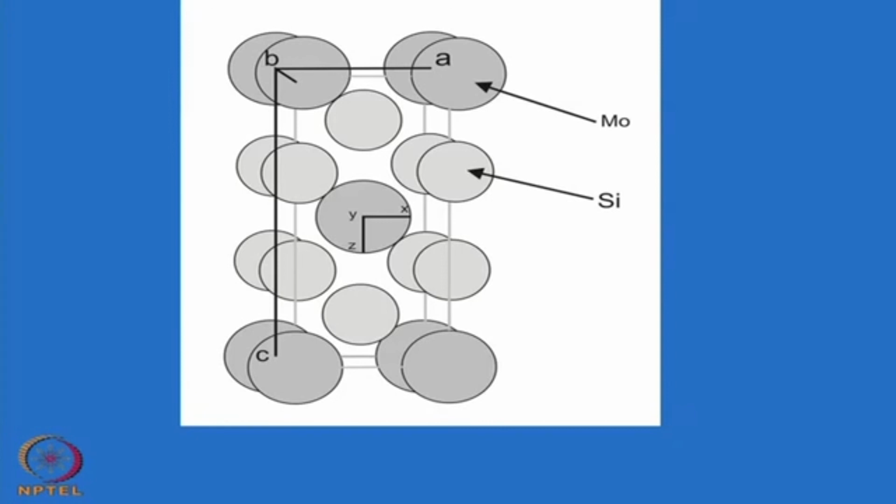Silicon carbide can be used up to a temperature about 1400 to 1500 degrees centigrade, whereas if you still need a higher temperature, molybdenum disilicide is the answer. So, most of the laboratory furnaces or even industrial furnaces, if you want to go beyond 1500 degrees centigrade up to about 1700 or 1800 in some cases, molybdenum disilicide is used as the heating element.